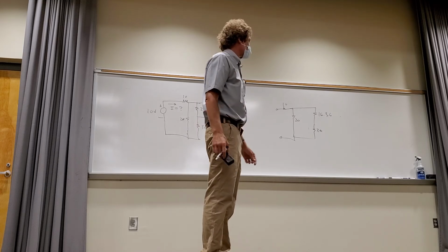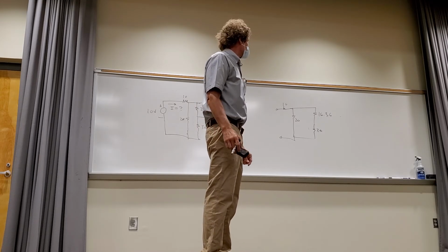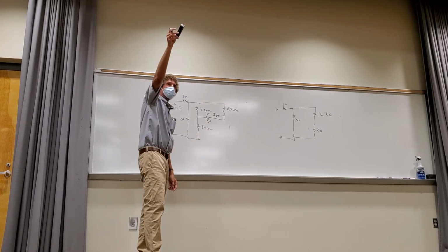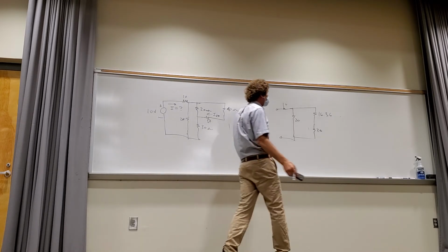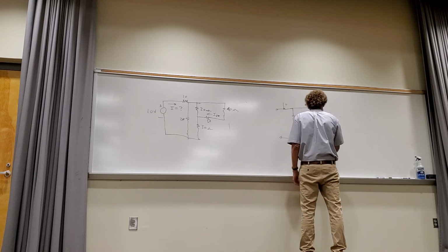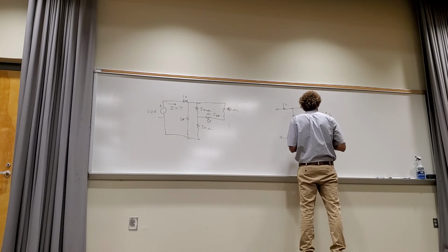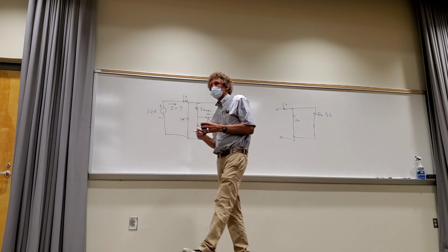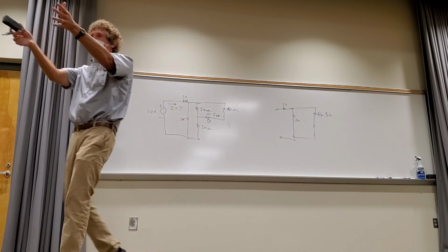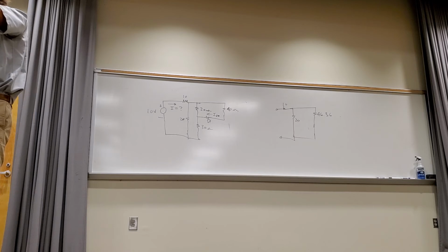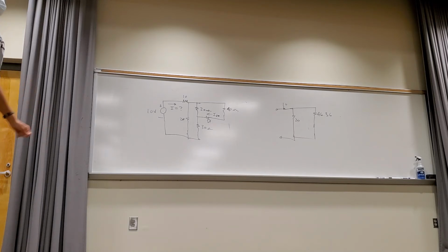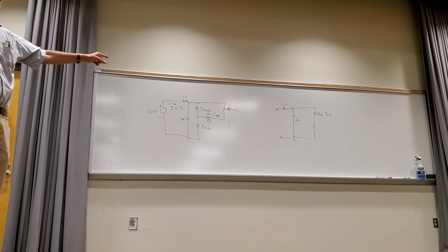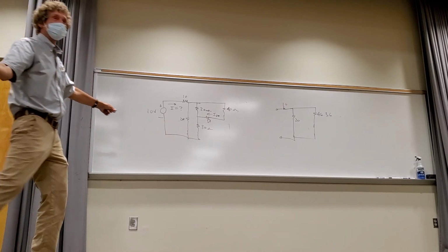What do I do? The 16.36 and the 30 in series. How many see that? Far back? You guys got it? So I'm just going to add this up and make that 46, right? All right. We're getting down to the point. How about this side of the room? Anybody? What's the next step? The 46.36 and the 20 in parallel. Can you give me that? 13.97. What is it? 13.97.